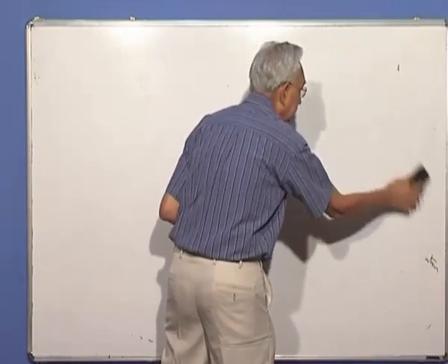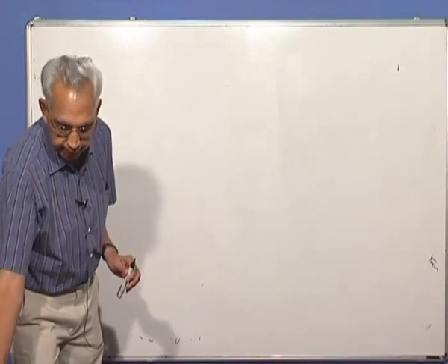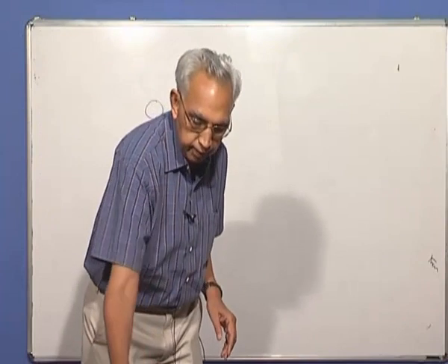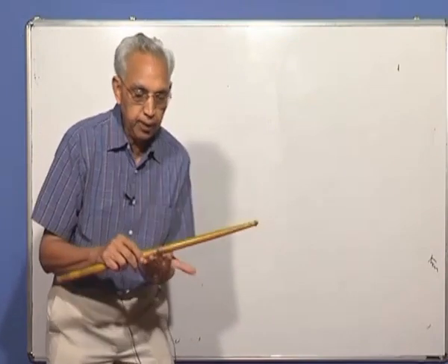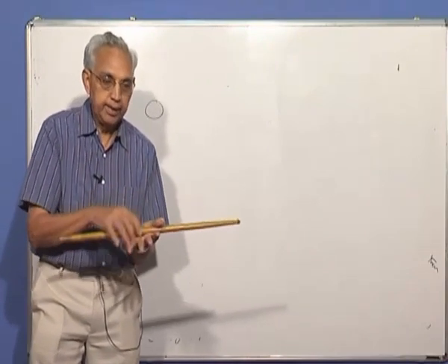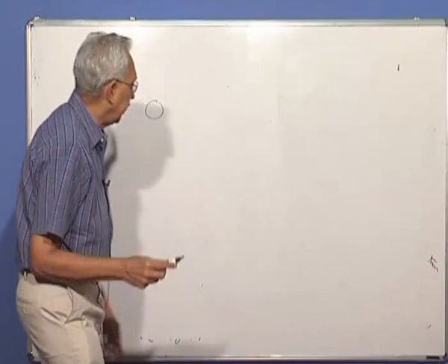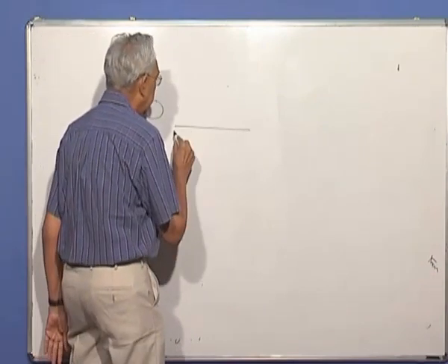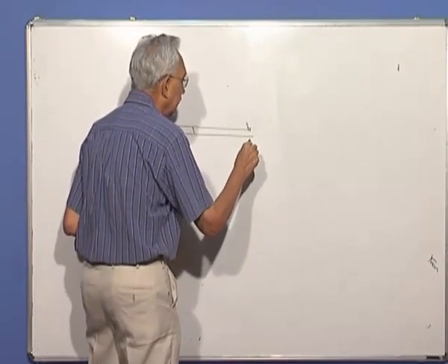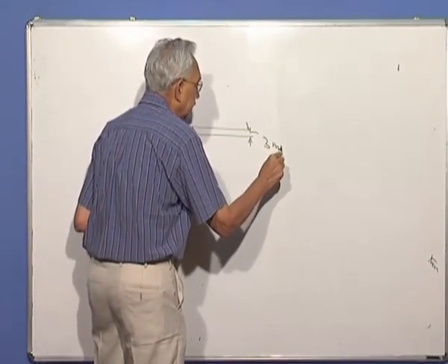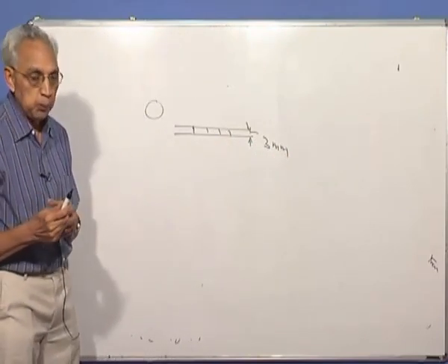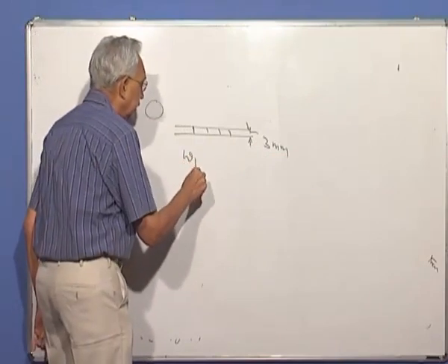different to determine. I take a pat of soil, a small piece of soil, and then I try to roll it something like this, so that I get a thread, and when the thread breaks, say this is the thread, you can make it finer, but once you reach something like 3 millimeters, if it starts breaking, that means it's becoming brittle. That is the plastic limit.